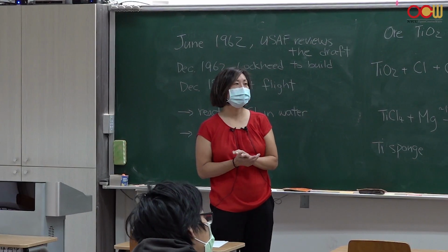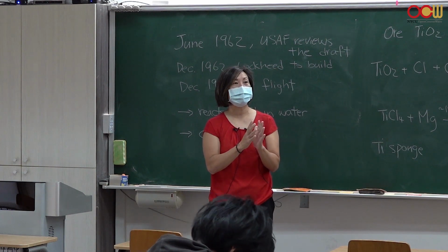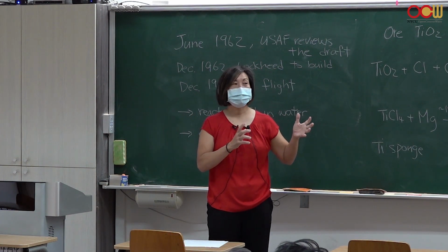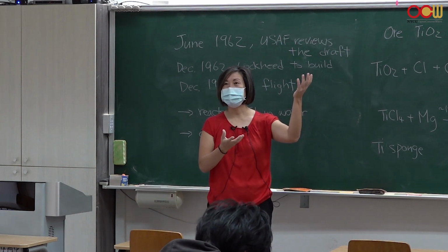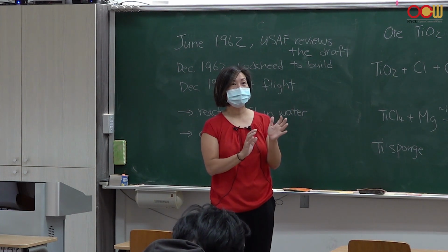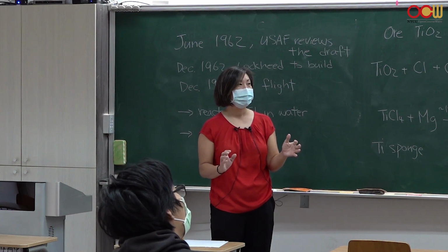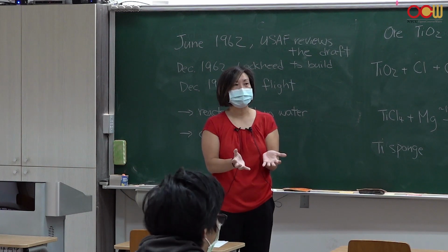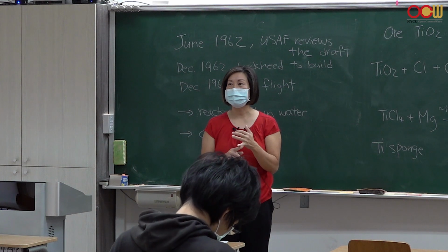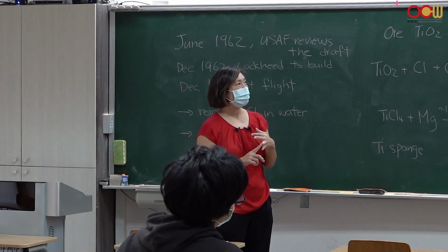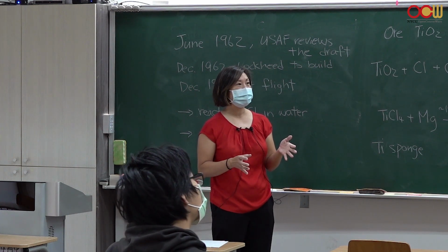So they chose beryllium as the mirror, the backing of the mirror, not the reflective part, because it needs to go from launch temperatures, right, high temperatures, into space, which is very, very cold, without changing its shape much. So it can't expand and contract like titanium does, because then it will ruin the configuration of the mirror. So it needs to be able to hold its shape. It needs to be very light, and then it needs to be very, very stiff. And so beryllium fits all of those things.